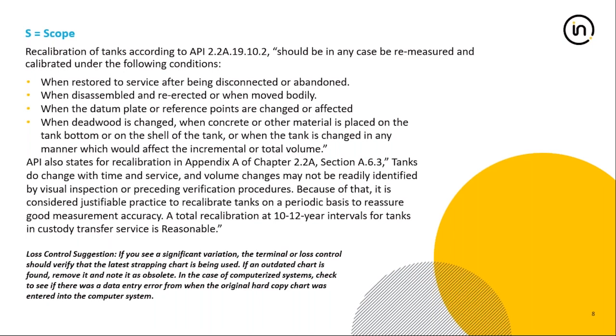That's why when you have a new tank installed, you need to first do the leak testing before you can do the calibration, because filling the tank with product is going to warp it a little bit, and so the measurement is going to change a little bit.